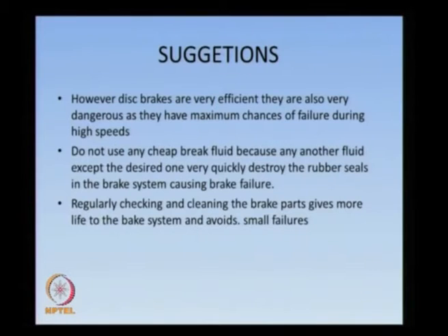However, the disc brakes are very efficient. They are also dangerous as they have the maximum chances of failure during high speeds. So never use any cheap brake fluid because of the chance of failure. Regular checking and maintaining of the brake pads gives more life to the brake systems and increases the efficiency.